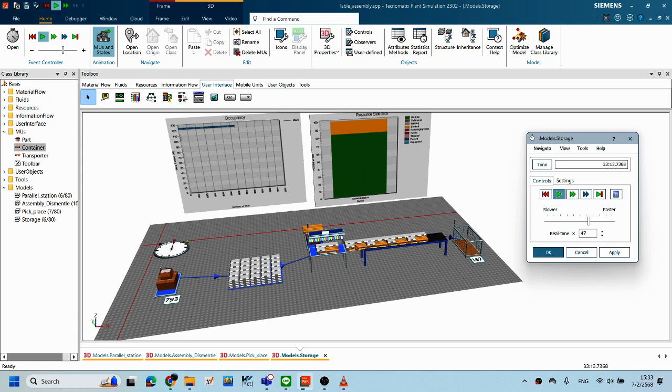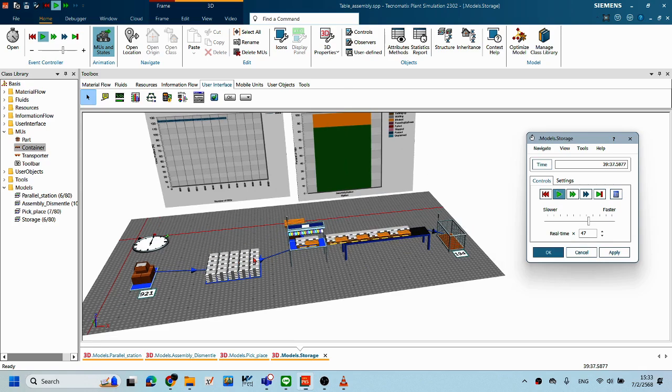in this process, one time the assembly station needs just only 4 parts, and why keep inside the storage 125, right? It's always full storage all the time, but actually in the assembly station, one time needs just only 4, and that means the storage is overstock, right. Overstock, you think about this, analyze this system, okay, not good, right? It's not good because you waste time, waste cost to keep this storage, right.